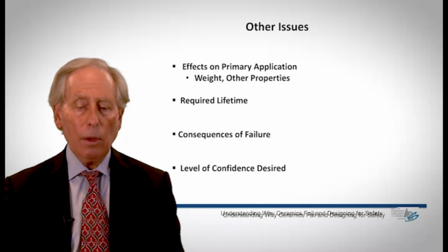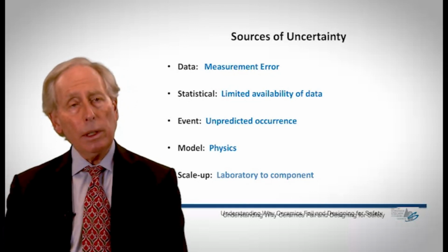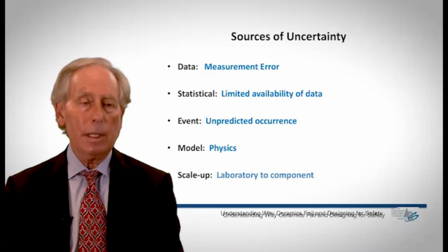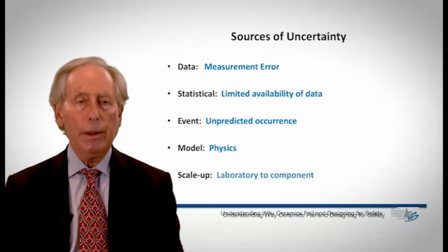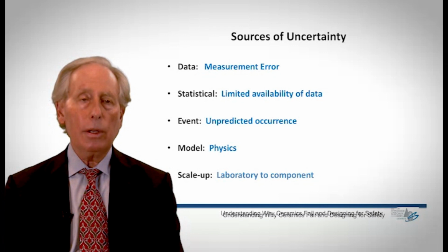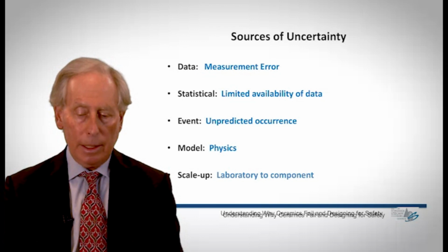We also have levels of uncertainty over what we're doing. What are those sources of uncertainty? We're going to go in the laboratory and make measurements because that's the way we can develop the data to predict what might happen to my material. But there's always measurement error. One can't avoid it. There will be uncertainty, and particularly in strength measurements, and I will talk a lot about that later. There are uncertainties in every strength measurement that I make for one reason or another. So what I call that is measurement error.